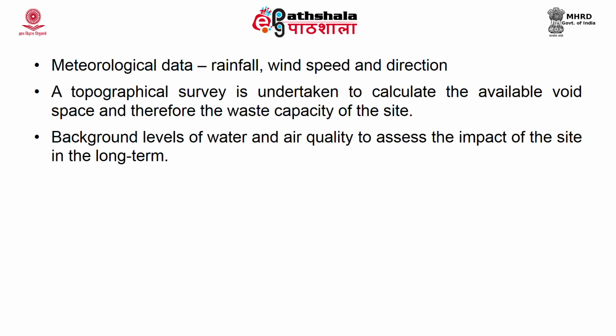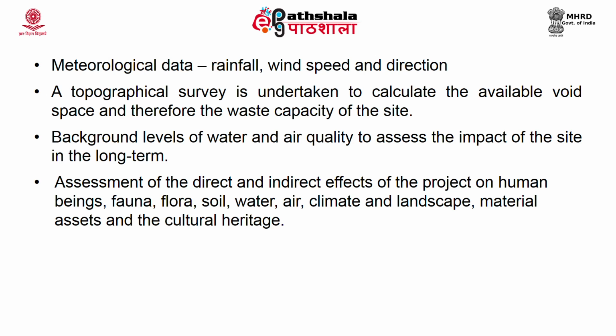The background levels of water and air quality should also be assessed to find out the impact of the site in the long term. For example, if you have this data about the water and the air quality, after some time when the landfill is closed, if you find some unusual changes in the air and water quality, this will help you find out whether there is any leakage or any problem in the landfill site. So, you should always assess the water and air quality before you select a site for the landfill.